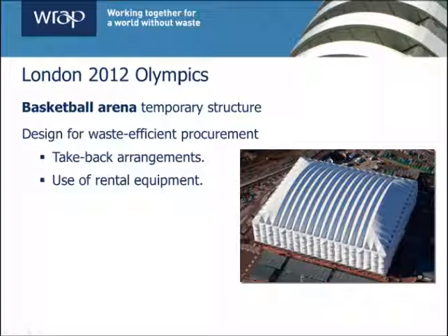3,000 tons of recycled railway ballast was used instead of virgin aggregates in the vibro stone columns for the arena's foundations. This foundation technique also produces minimal amounts of excavated material. 80 tons of second-hand steel piles from a local source were also used, contributing to achievement of the project's recycled content target.